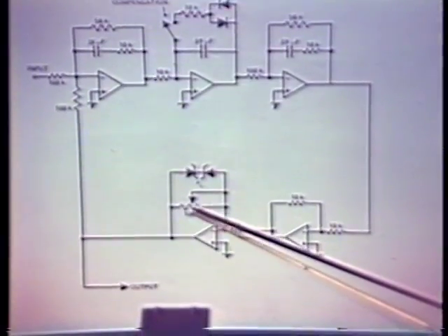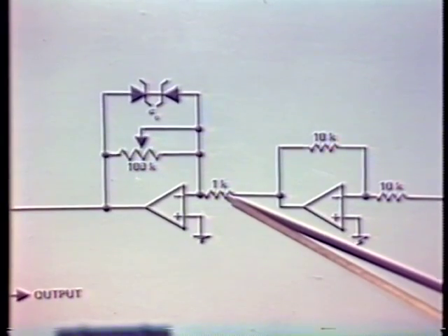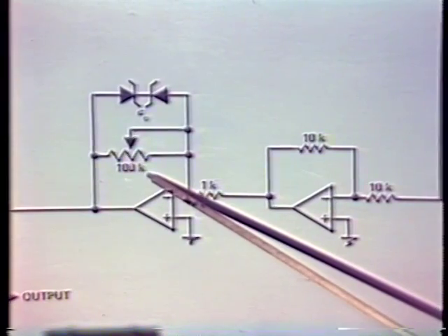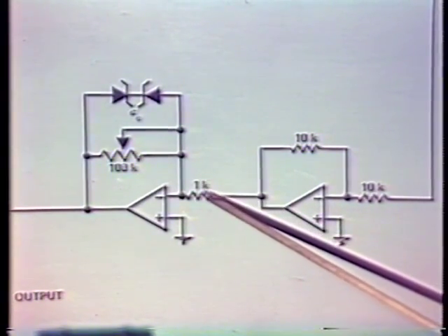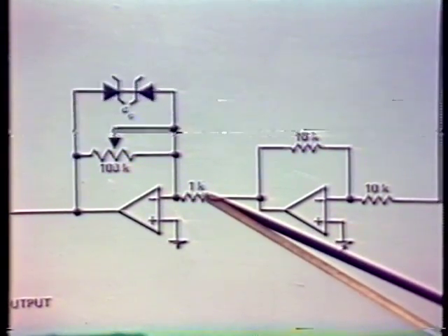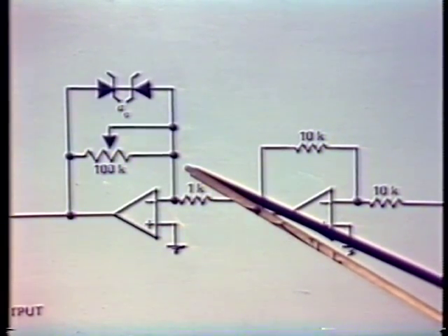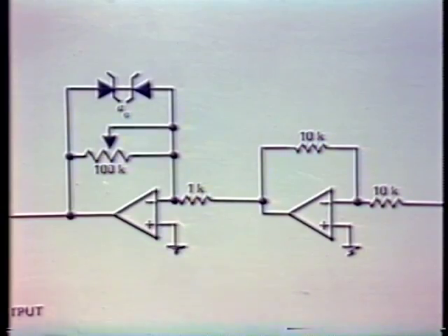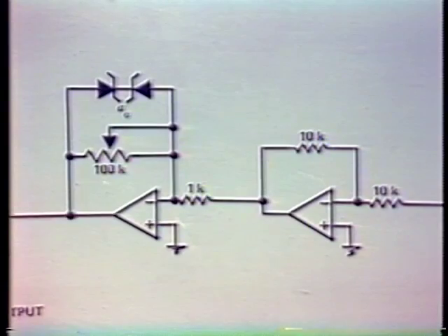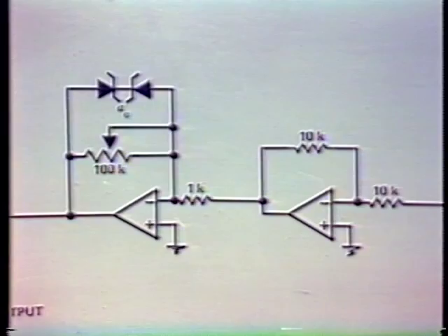We have a limiter, and we make the limiter in a very simple way. We have the usual inverting connection operational amplifier with a 1K input resistor and a potentiometer for the feedback element. The gain of this configuration is simply the negative of the feedback resistor divided by the input resistor. So by adjusting the potentiometer, we can change the gain from basically 0 to -100. Actually, in the actual test setup, we have a little series resistor included with the potentiometer so that we can't make the gain of this block really 0. We can bring it down to about unity.